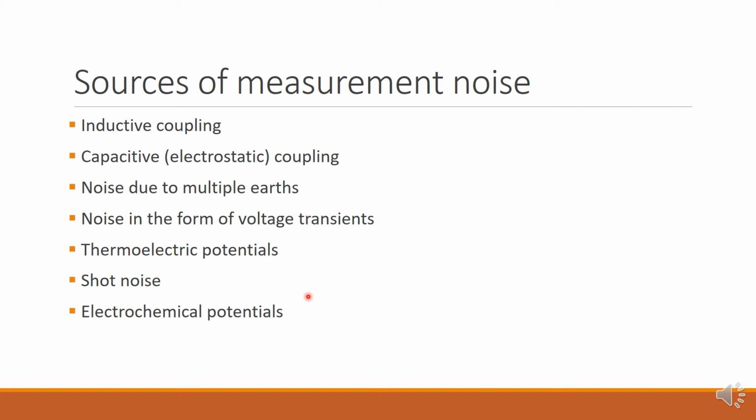So as I said earlier, noise can be generated from both external and internal sources. It will disturb your measurement system. Internal sources include thermoelectric potentials, shot noise, potential due to inductive coupling, capacitive coupling.